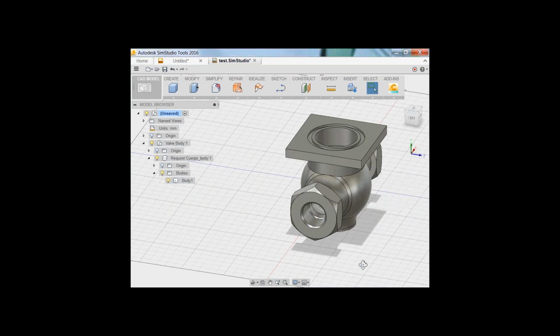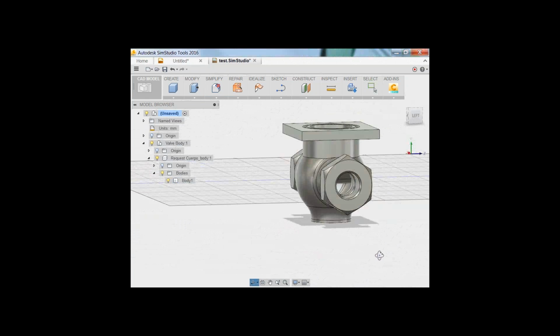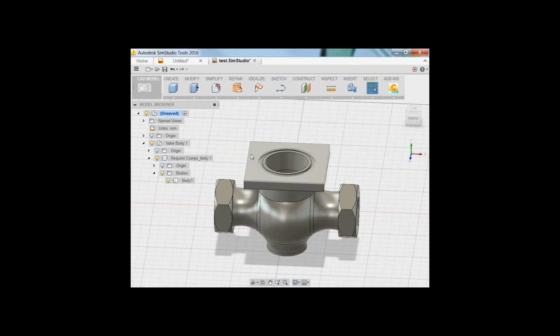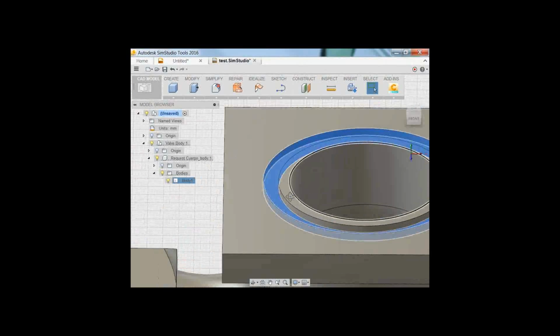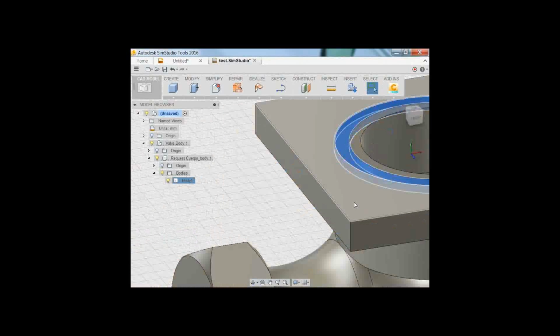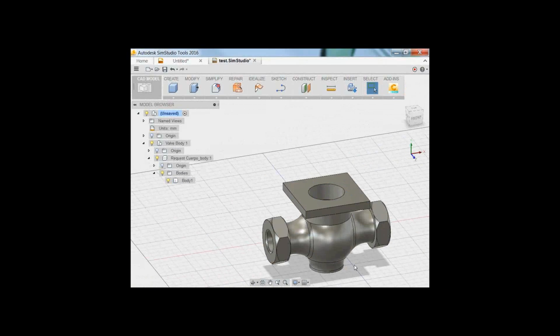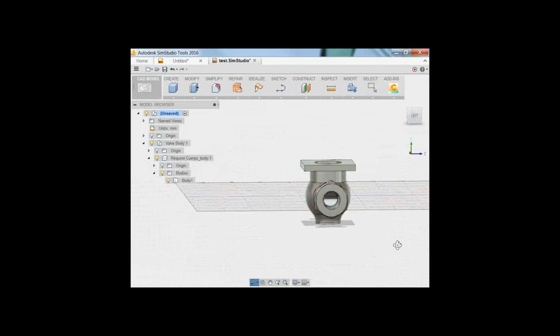And yeah, so that was a good example of just pay attention to what you're clicking. I almost deleted a lot more than I really needed to right there because the Remove Faces chain selects things. So right now I got rid of my threads, I got rid of that, and up here I'm just going to get rid of just that kind of offset here. So we'll click all three faces because that'll go ahead and delete the thing fully. And that was a good example of, you have to chain select things correctly in order to use just the manual delete key. So now we just have kind of a plain geometry valve.